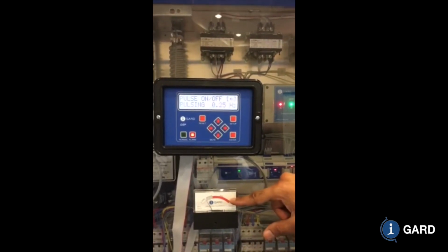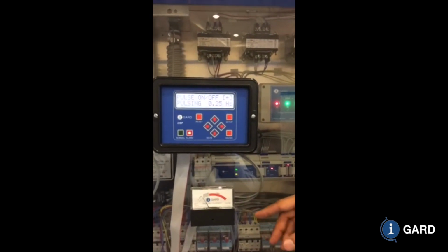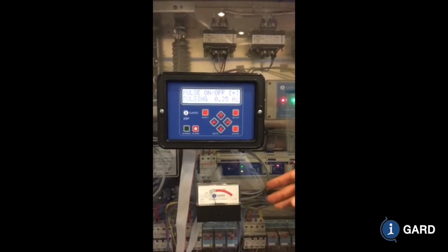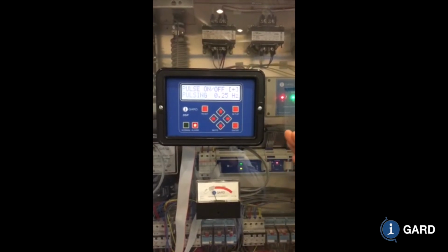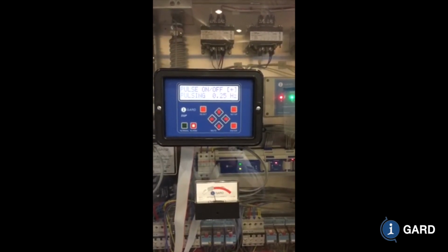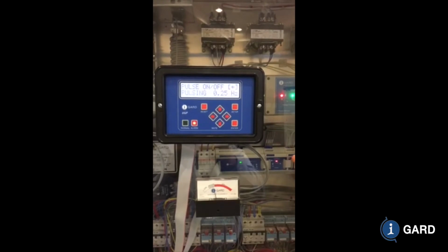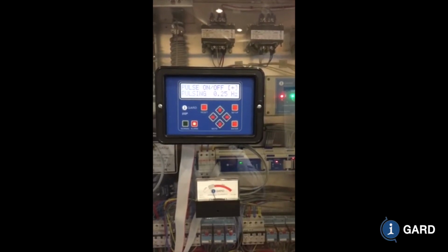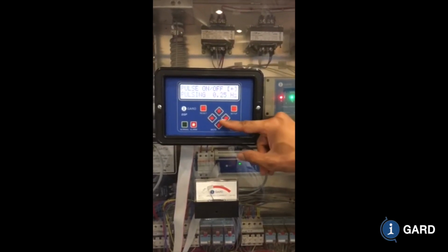When we place a current sensor around all 3 phases of a feeder, any feeder on the system, if we don't see that pattern, that feeder does not have the fault. But if it has the pattern, then we know that that feeder has the fault. The fault is on that feeder somewhere.